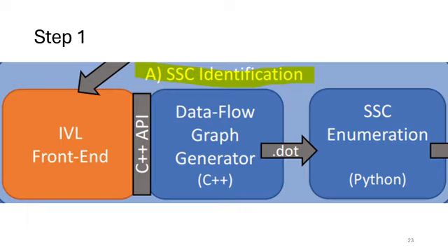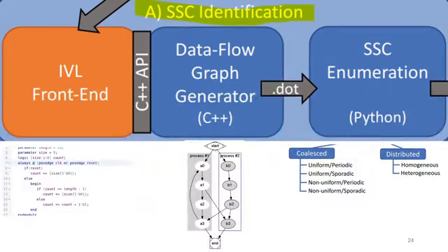So, step one is pretty straightforward. It looks for any collection of flip-flops or latches or registers. It looks through the Icarus Verilog front end and creates a data flow graph with a custom C++ API to see the bit level signal dependency, which highlights state-saving signals that are gated and intermediate signals from combinational logic. It can even work with procedural assignment expressions like the one you see on the left there, because it uses template matching like a lot of HDL compilers already do.